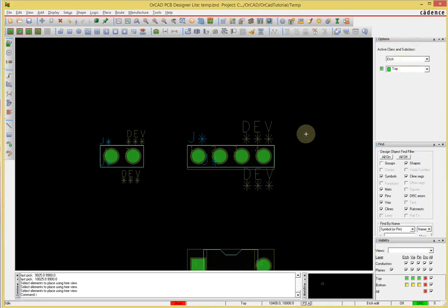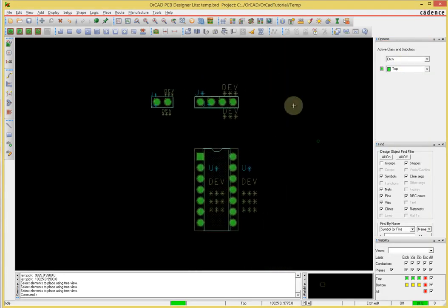Another good strategy is you can print. Many people, and I do this myself, print what you have here onto a sheet of paper and make sure that the scaling of the print is 1:1. That means the exact dimensions of the printout will be exactly as they would be if you actually had the board fabricated.